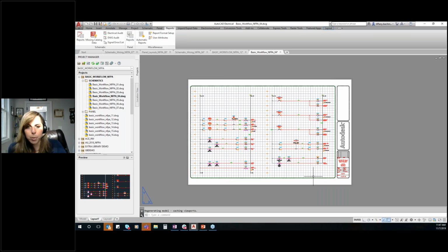You shouldn't be scaling them up or down around your drawings. While I understand schematics are not really full scale, your panel drawings or your physical representations absolutely are. And all of that should be done in paper space by putting a viewport into your title block. Very, very easy to do. Very, very important, I think, to getting the proper setup to how you actually want these to plot as well.